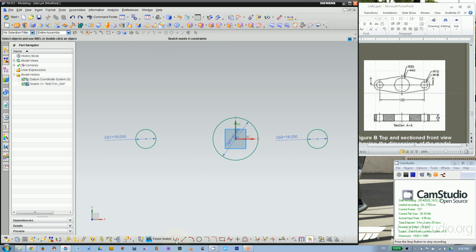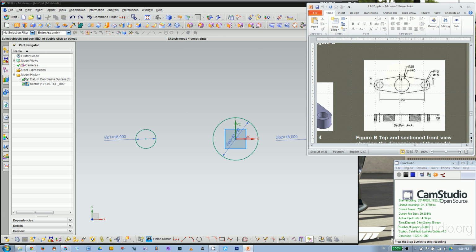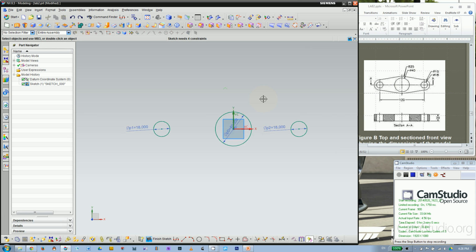Don't ever try to use profile tool to draw something like this. This is very tedious. Okay, and the fast way is, if you look at anything like this, for the top and the bottom, you can use fillets. For this side, you can just put 2 circles and trim them off. You can also use fillets, but that's kind of too long for a sharp corner.